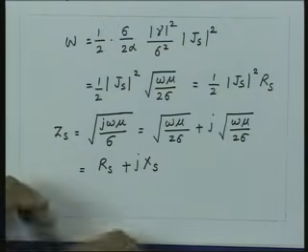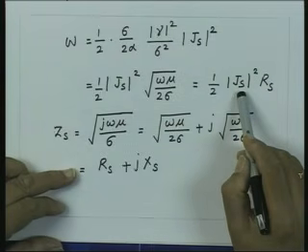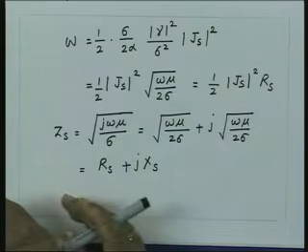If I know the tangential component of the magnetic field on the surface of the conductor, I can find the linear surface current density using the relation n cross H, and once I know the surface current density and the surface impedance, I can find the power loss per unit area of the conductor. So, this calculation of power loss using the surface impedance or surface resistance and the linear current density is extremely useful in calculating the power losses in conducting media.